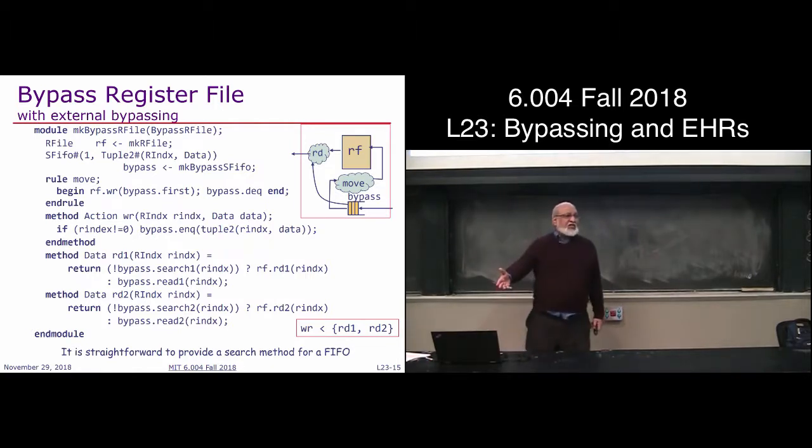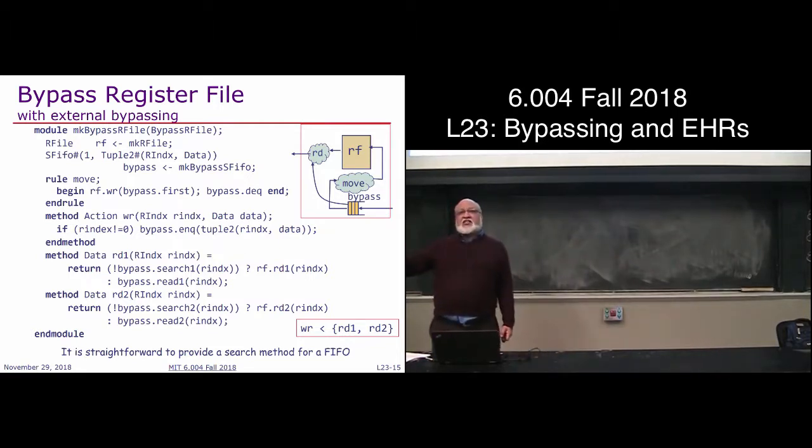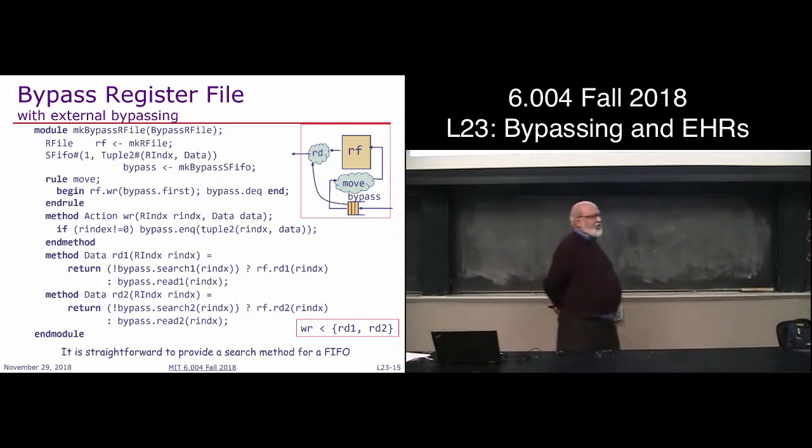So we will have a register file designed this way. And now, if we really want to be honest, we should go and synthesize a register file using EHRs and synthesize a register file using this stuff and see what their properties are, which takes more area, which has better delay and so on. So don't take my word for it. If you want, go and synthesize both these things and you'll see the difference.